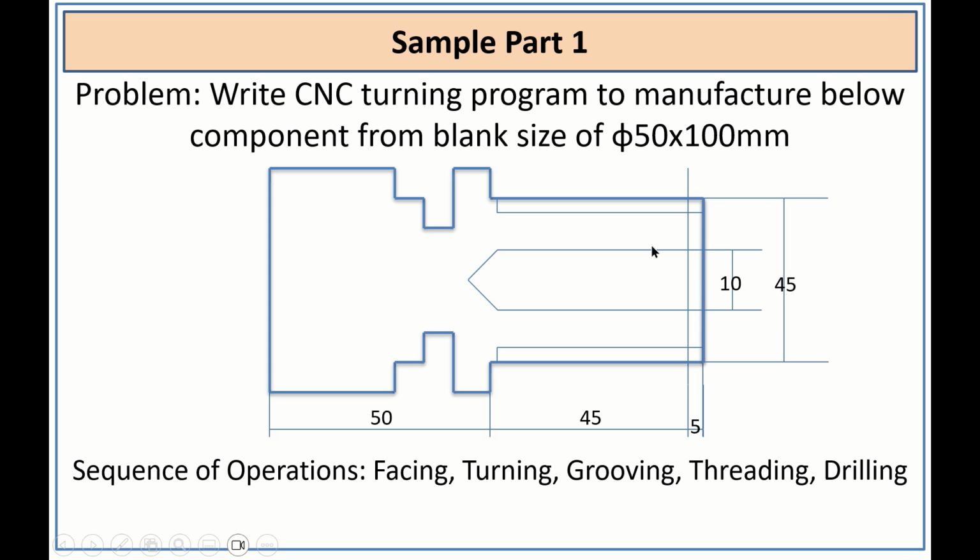First we need to perform a facing operation, then a turning operation, then grooving, threading and drilling. So this is the sequence of operations we need to perform, and we need to know it well before you start the programming.